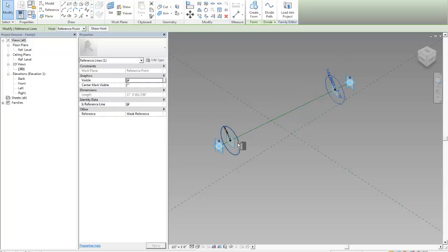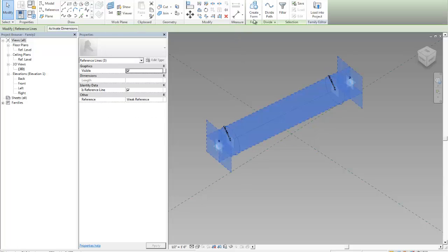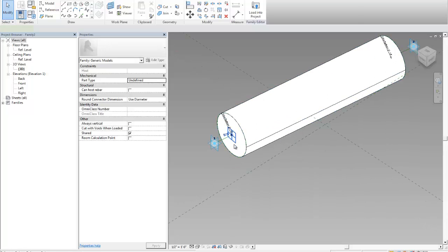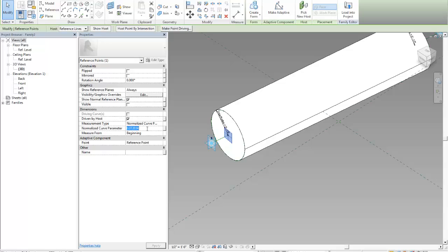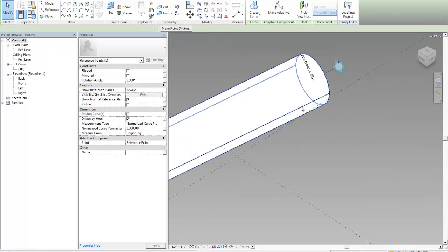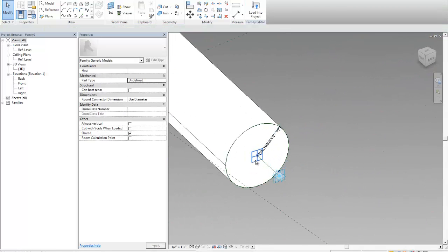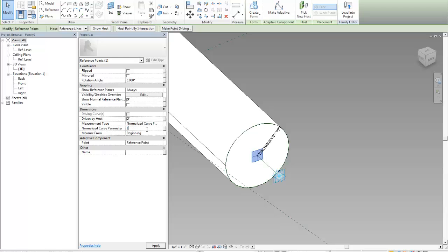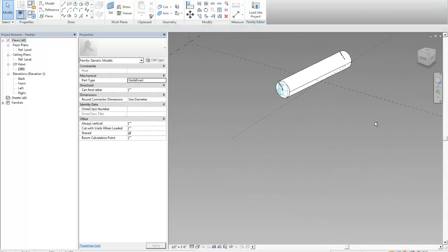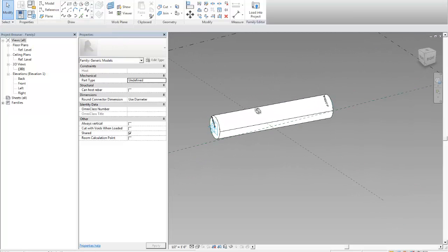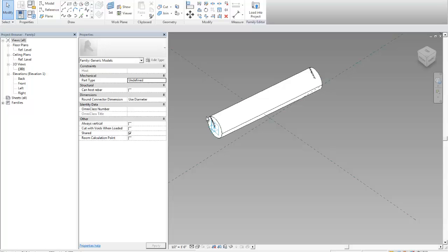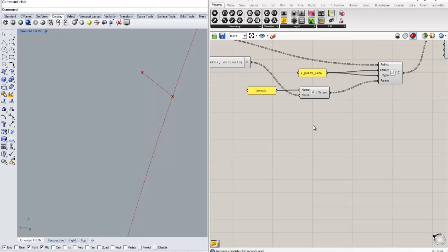And then if you select those, and then create form, it gives you form, and then you got that pointer you can push around on that line between those 2 points. So one of them is going to go in the beginning, and one of them is going to go at the end. So once we have that, we just gotta make sure that we add that parameter to it, and then make sure we save it as that.